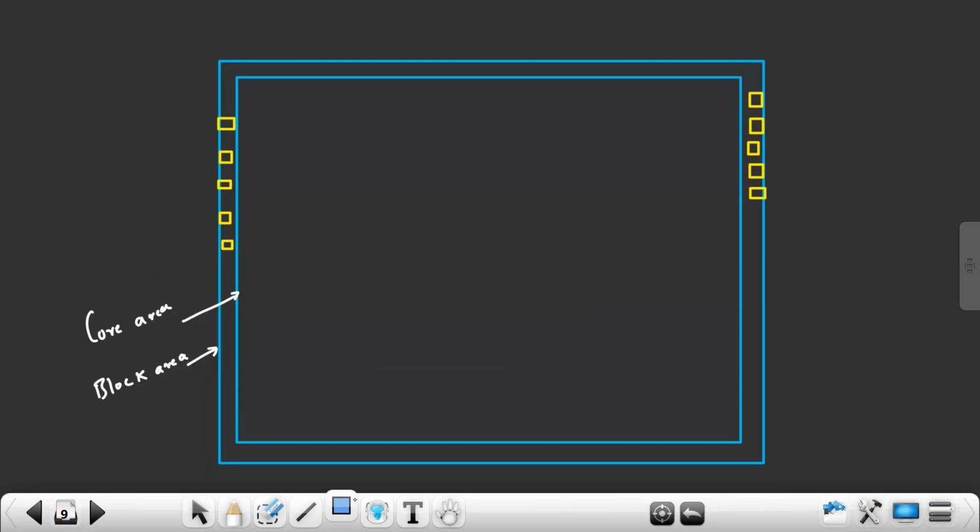If your engineer is telling you to place the input ports on the left, you have to place all the input ports on the left, and all the output ports on the right. Sometimes he will place the ports himself and give you the location. You can just source the file and it will place the ports. If he tells you all input ports on the left and all output ports on the right, then how to place them? Everything we discuss here in port placement.